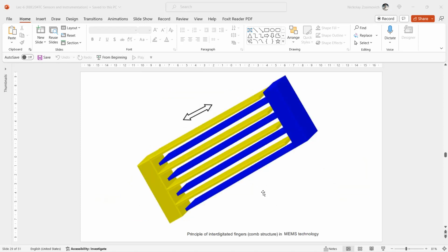Micro-machined acceleration sensors suffer from small capacitance too, and hence have low sensitivity. A large initial capacitance might be realized by a dielectric support structure. See the preceding section on a pressure sensor. Another way is to increase the effective surface area. This is realized in MEMS technology, allowing the construction of so-called comb structures, and this slide shows the basic configuration.